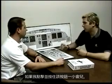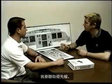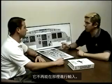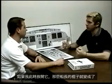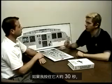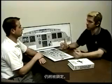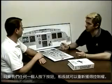If I click and hold that button for a short period of time, I'm going to hear the words, and in my case, as a first officer, I'm going to hear "priority right." And what that means is that the captain's stick is now deactivated. It can no longer make inputs. If I let go of it at this point, then the captain's stick becomes reactive, and it's the same summation that typically goes on. If I press and hold it for approximately 30 seconds, then it will latch out the captain's. In other words, I can let go of it after that, and the captain's stick will still be locked out. The captain can get his control back by either of us pressing our buttons.